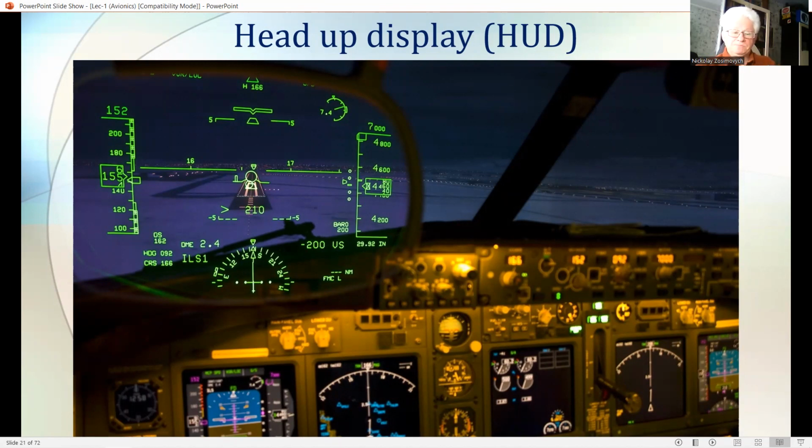The HUD can also display a forward-looking infrared, FLIR, clear video picture one-to-one with the outside world from the fixed FLIR imaging sensor installed in the aircraft. The infrared picture merges naturally with the visual scene, enabling operations to be carried out at night or in conditions of poor visibility due to haze or cloud.